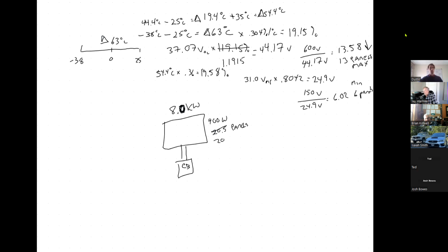If you're wanting more production, you could go with 22 panels and have 2 strings of 11. That's fine. A lot of these are guesstimates anyway. But I wouldn't go with 3 strings of 7. That would just raise costs unnecessarily.